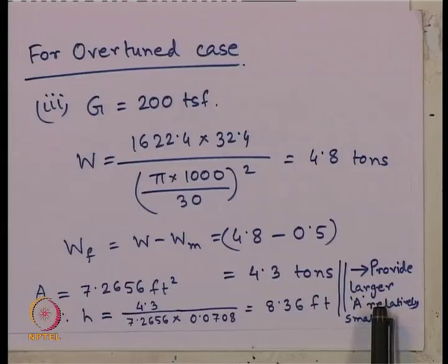You can try with say 200 mm thickness of the footing, then how much area is required. Let us say you keep all around same clearance. So, you will get the idea of area, and your width to breadth ratio based on your size of the base plate is known, you will get the dimensions and convert them to close possible multiples of that 25 mm.